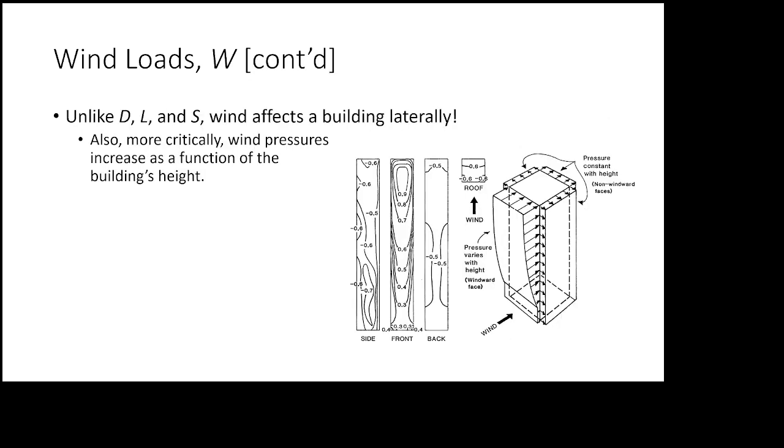The other thing about wind loads, and this is about both lateral force effects that we have to deal with, wind and seismic, they are adversely impacted by the height of the building. When you're designing for gravity loads like dead load and live load, designing a floor beam on the 2nd story is exactly the same as designing a floor beam on the 82nd story, because gravity load doesn't change. But as the building gets taller, the lateral forces tend to get larger.